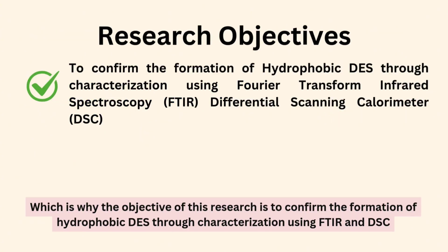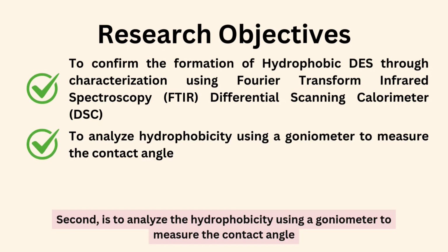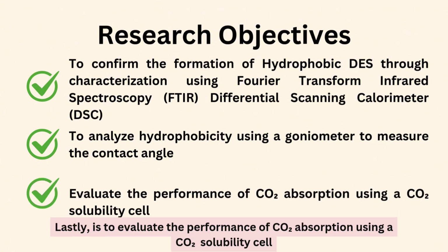Which is why the objective of this research is to confirm the formation of hydrophobic deep eutectic solvent through characterization using FTIR and DSC. And second, it is to analyze the hydrophobicity using a goniometer to measure the contact angle. Lastly, it is to evaluate the performance of CO2 absorption using a CO2 solubility cell.